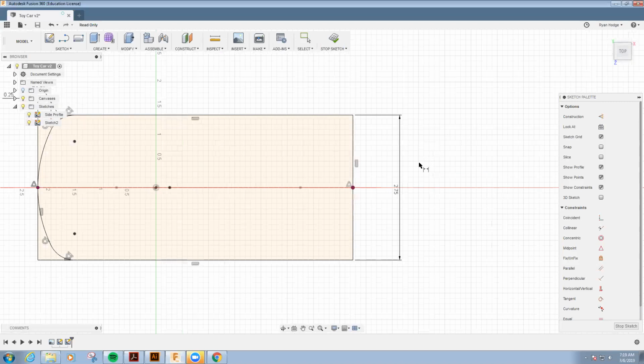I'm going to do the same thing on the back side. I'll go to sketch, arc. And I don't necessarily want these to be mirror images of each other because I think the back end of the car might be slightly different than the front end. So I'll start my series of arcs. And if I don't want to keep this tangent constraint, if I hold Control on the keyboard, it won't snap to a tangent. But I do want that tangent constraint, so I won't use Control.